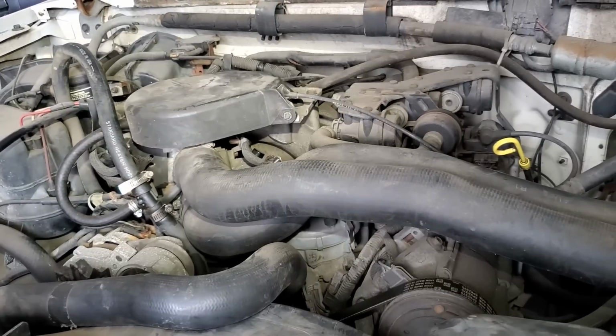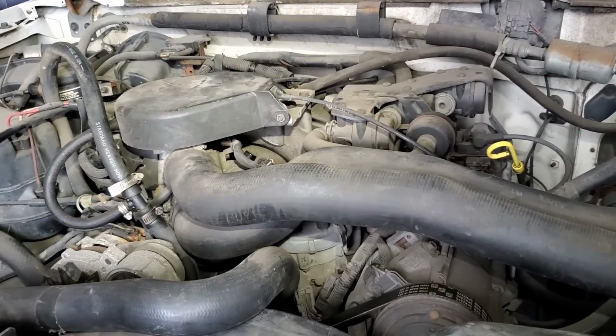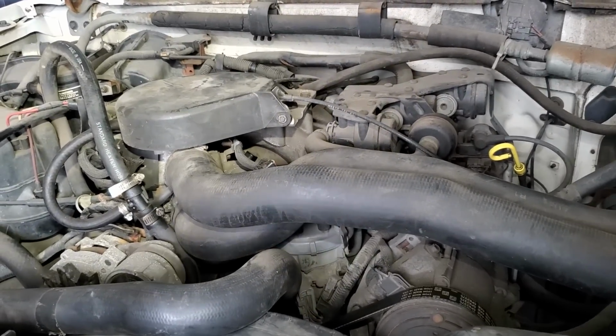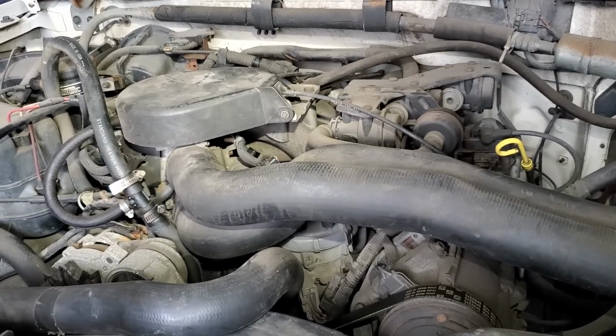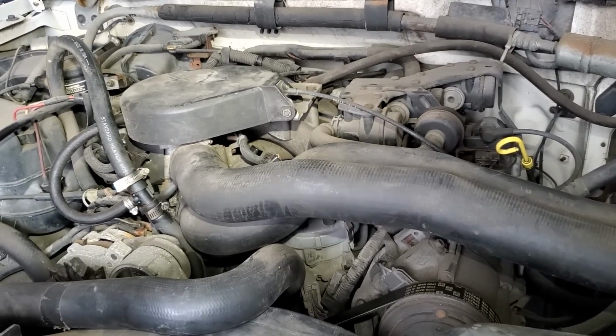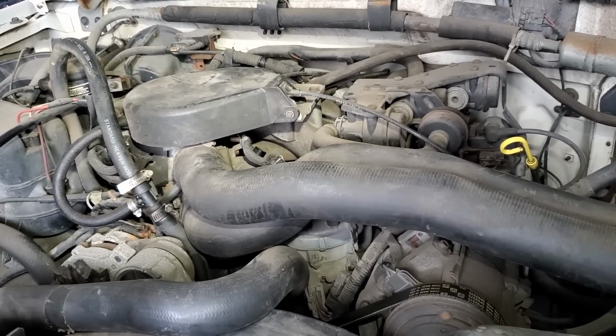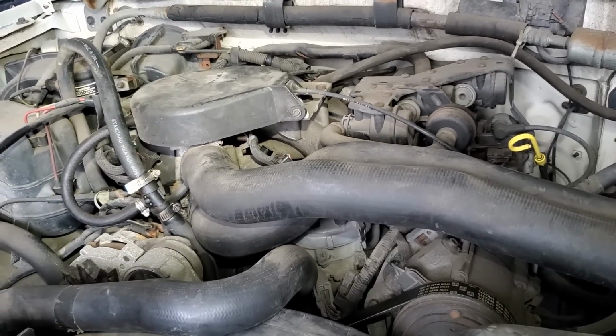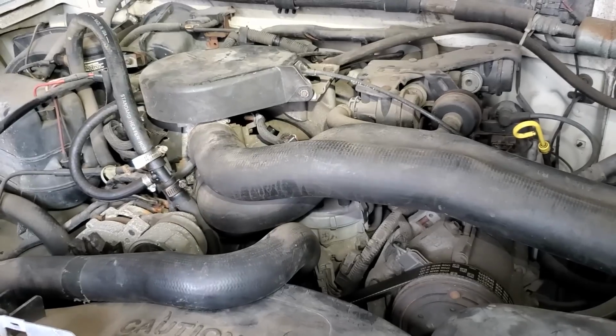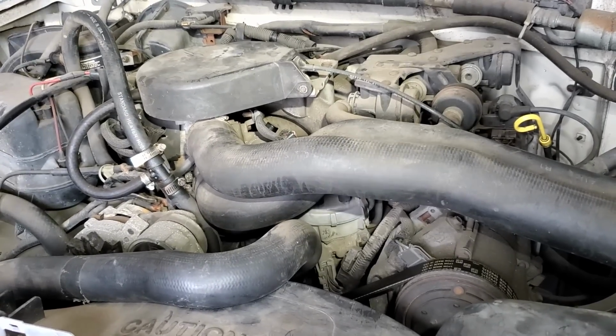So this being a heavy-duty vehicle over 8,600 pounds will probably have a NOx limit of like 2,200, which if this was, say, 6,000 pounds, it would have a NOx limit of like 500 parts per million or 550. That comes up later in the video.